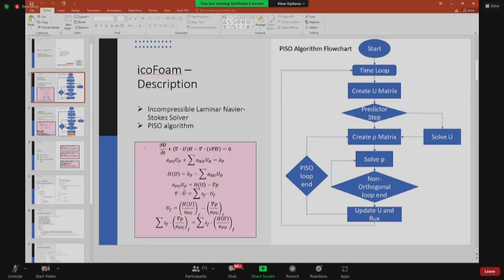When you integrate this continuity equation over the control volume, it changes to a divergence scheme with Sf dot Uf, where the predicted velocity field Uf is interpolated from the previously calculated velocity field. If you do that, you get the Laplacian equation for pressure, which we solve in the p equation.